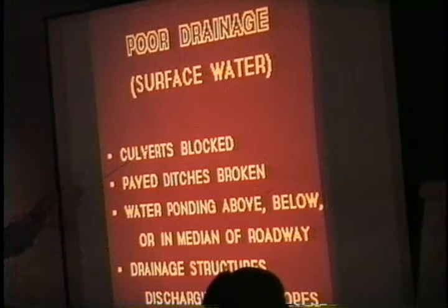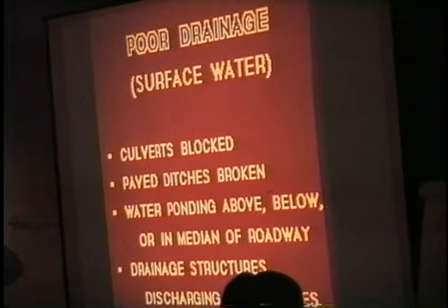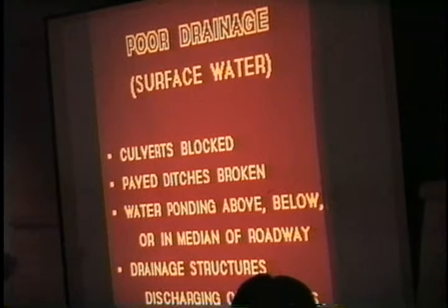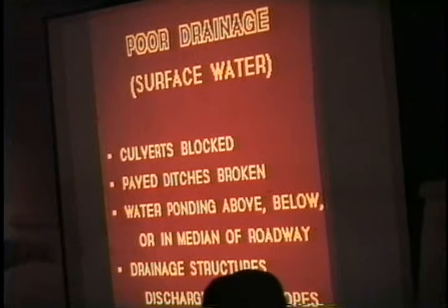It's sideways if you have the minimum of 2% on a straight road, and if you have some curvature, it'd be super elevated a little more. But it also drains longitudinally at the ends.